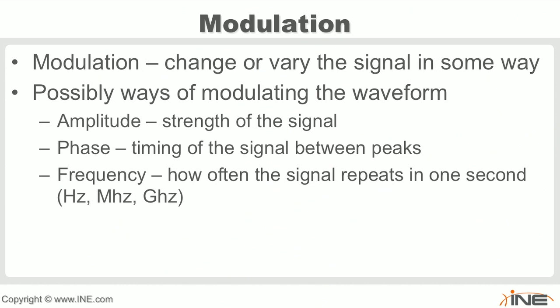But when you switch to AM and FM, really what you're saying is anytime you have an AM FM radio, you have two separate radios that are receiving in very different ways. One is receiving based on knowing how to decode and understand the modulation of the power, the amplitude, and one is able to decode and understand the modulation or the change in frequency. There's also phase modulation. Okay, so I can actually change the timing of the signal peaks.